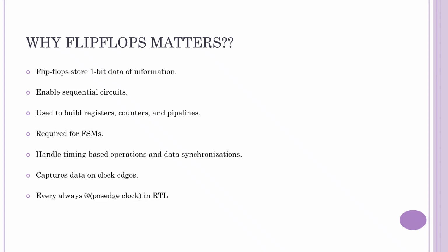Second, they make sequential circuits possible. There are two types of circuits: combinational circuits, which depend only on current inputs, and sequential circuits, which depend on past outputs. Now, here's the key. Flip-flops store the past state. Without flip-flops, we could only build combinational logic, with no memory, no history, no state, no smart behavior.